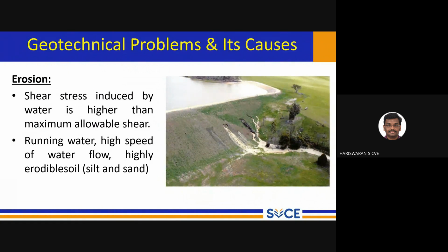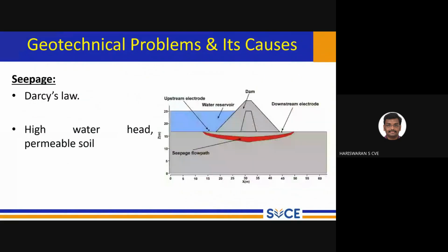Erosion is not happening only one time. Initially the impact is very less, but if it is happening continuously, a large loss of soil creates major soil compression and leads to differential settlement of the structure constructed above that, and the same thing happens to a structure constructed near to that. So erosion control must be properly identified. This happens whenever there is hydraulic activity: water, running water, stagnant water, retaining of water. In those aspects, we have to think about proper drainage, right?